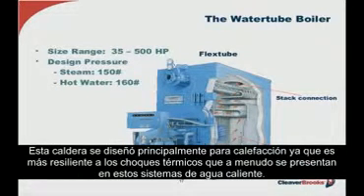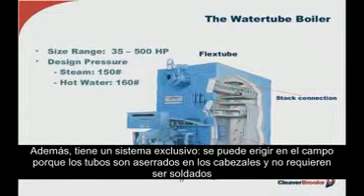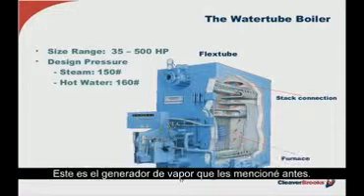This boiler was originally designed primarily for hot water comfort heating, as it was much more resilient to the possibility of thermal shock often encountered in these hot water systems. However, it was also found to be an excellent steam boiler and is applied in some process applications as well. It also has a distinct feature in that it has the ability to be readily field erected because the tubes are swedged into the respective headers, not requiring any welding.